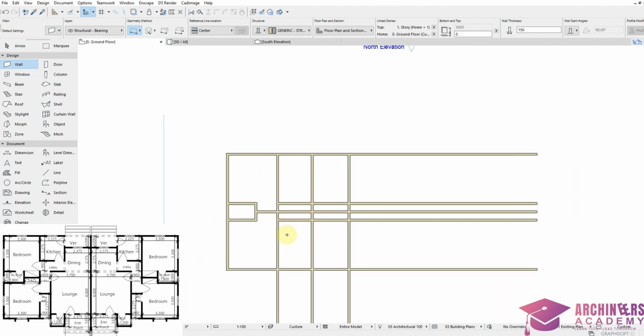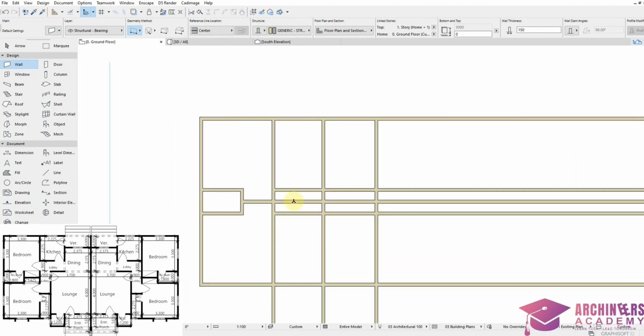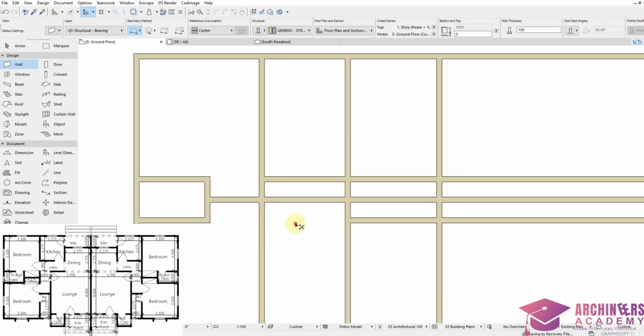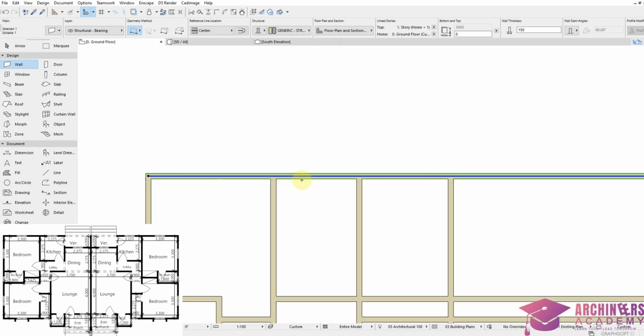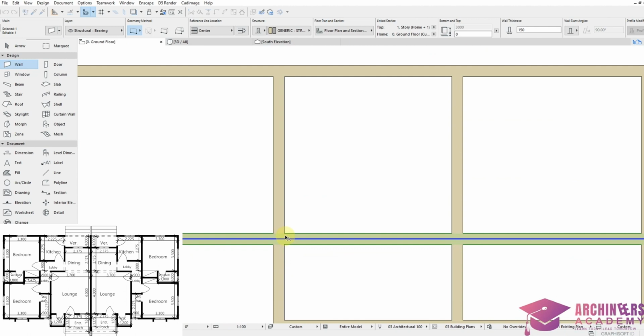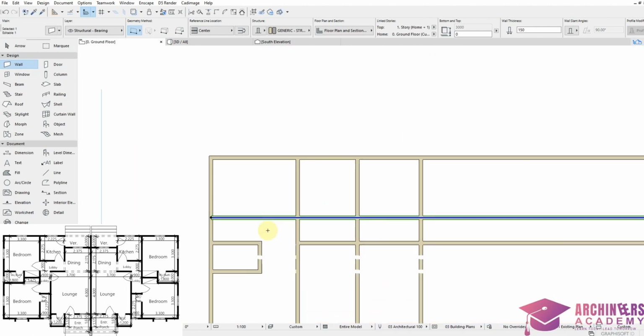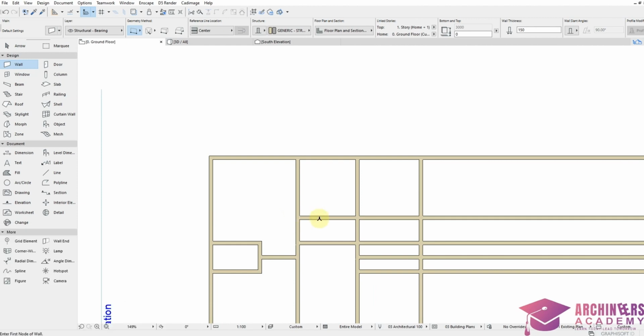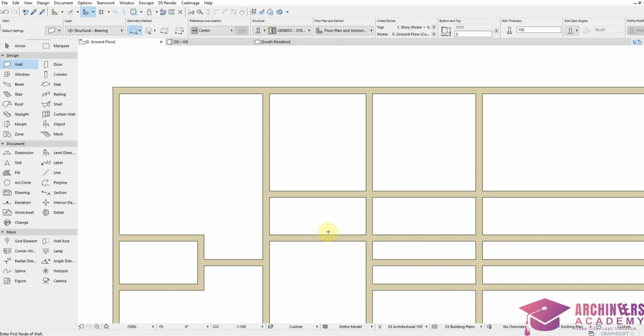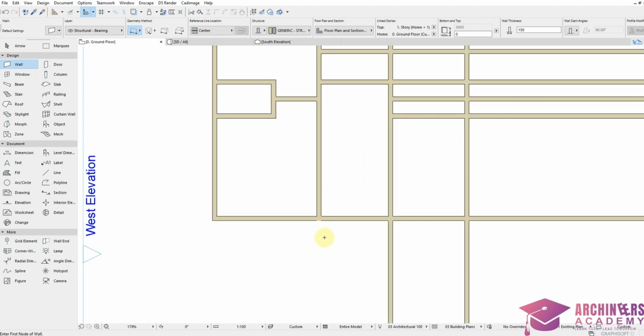Over to the next place, which is the kitchen. So all these lines are not needed. So start with the kitchen. The length is 2,275. Ctrl D to add the wall thickness. So remove the extra walls. Then we have a lobby right here of 900. Delete that using our Control key.